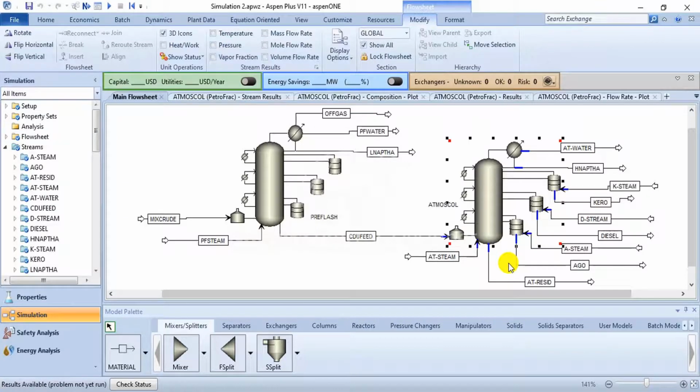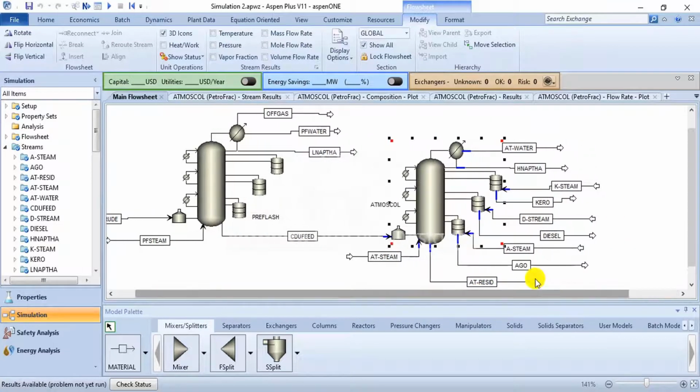The main difference from the atmospheric distillation unit is that the pressure is going to be lower now, and there will be some configuration changes, because the vacuum distillation unit is not as large as the atmospheric distillation unit. It's just to separate some of the light components in this residue. When you take it to vacuum, there will be a higher degree of separation.